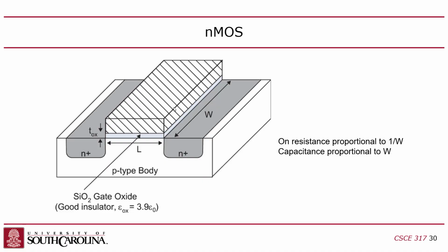Okay. Also, and I didn't mention this last time, but this is important. I mentioned that the channel is your minimum feature size. Why? Because the rate at which you can turn on a transistor not only depends on the capacitance, which of course is minimal when the plates of the capacitor are smallest, right? But the minority charge carriers that are attracted out of the substrate and come into the channel, right?